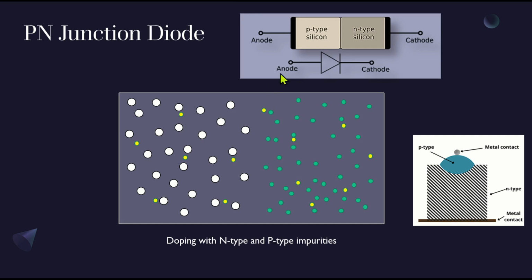As seen in the diagram, the PN junction diode is not actually just a combination of two semiconductors. It actually looks like this, as you can see here in this diagram. To generate a PN junction diode, first we consider an n-type material, and then in that n-type material we dope with holes, and a layer of p-type, or the doped holes, gets fused over the layer of the n-type material, which generates the PN junction diode.